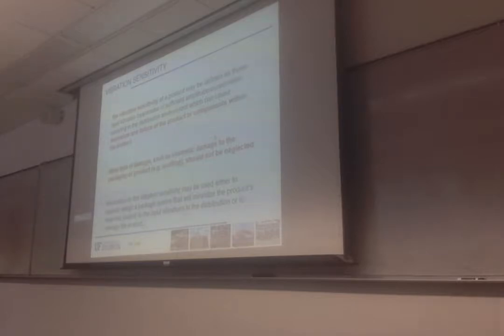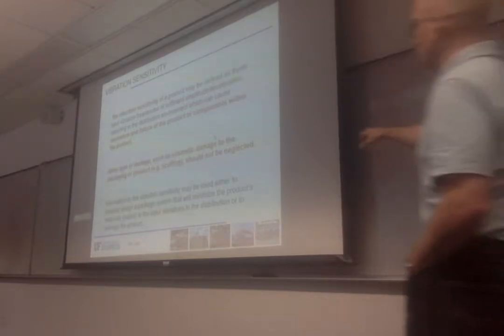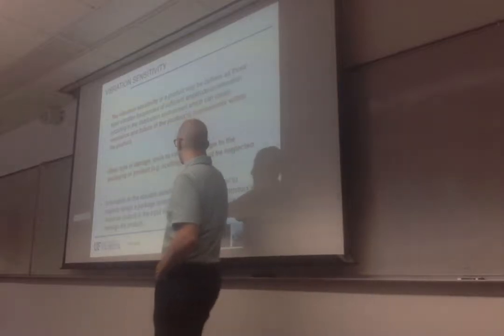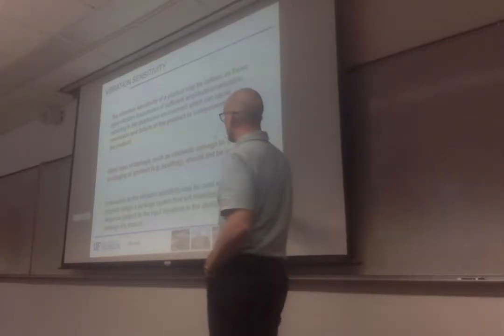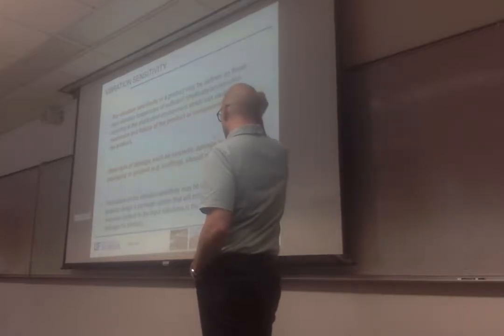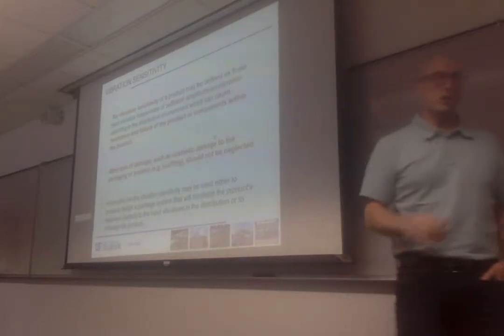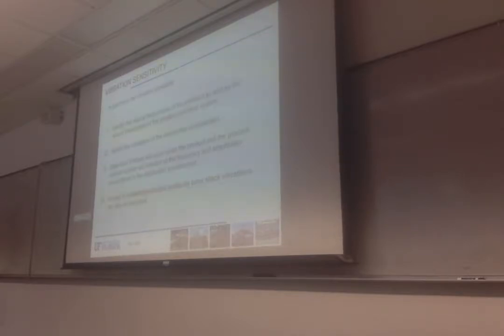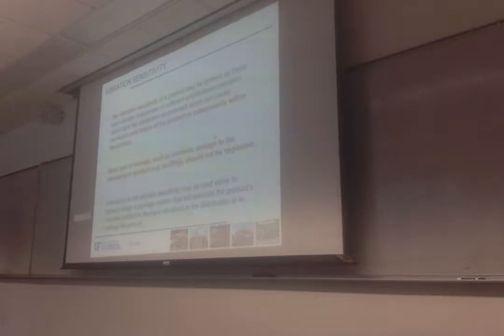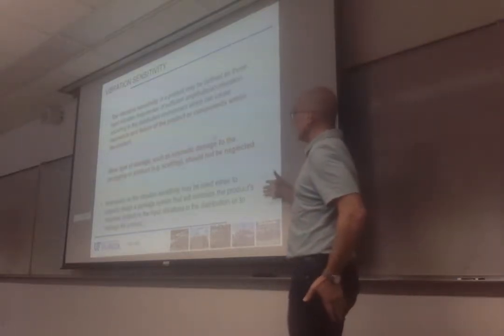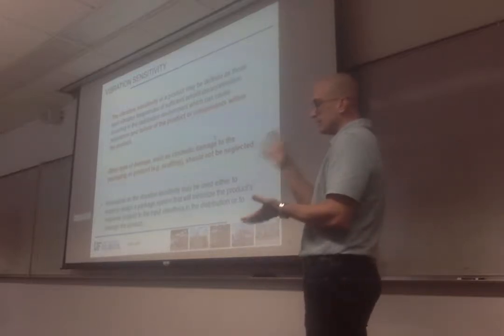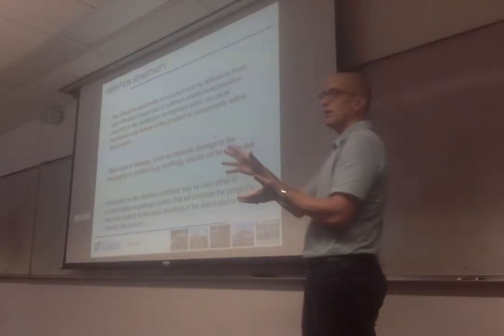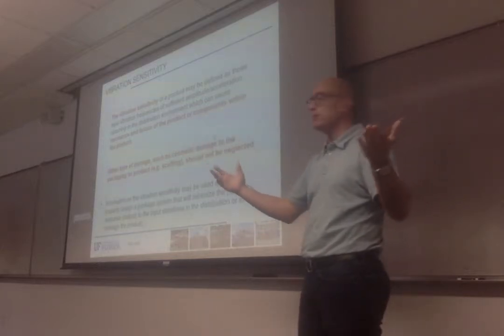So, let's see. Information on the vibration sensitivity is used to either properly design a package system that will minimize the product's response output to the input vibration in the distribution system, or to redesign the product. So, that means you need to look at this, okay, and see how you can adjust. And again, I talk about it a little bit later. You need to always think about these things at different levels, right? You need to think about it at a single box level or the product itself, but also at the pallet level, okay? Because these will be different.